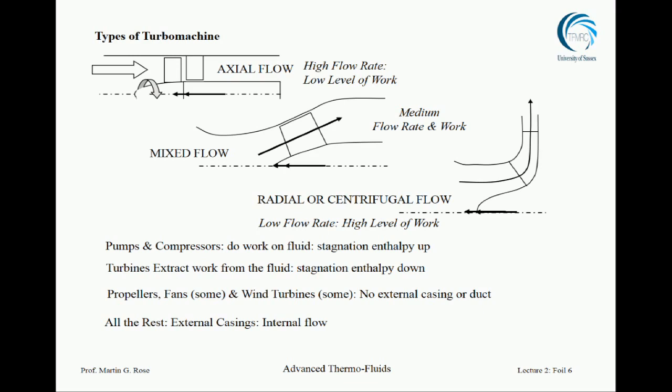The basic definition of what is a pump or a compressor is that it does work on the fluid. And what that means is the stagnation enthalpy, formally, if you're into thermodynamics, the stagnation enthalpy of the fluid rises. That singularly is what a compressor is. A turbine does the exact reverse. It extracts work from the fluid and the stagnation enthalpy drops. So if you want a definition of what determines whether it's a turbine or a compressor, look at the stagnation enthalpy, which is to say the total temperature.